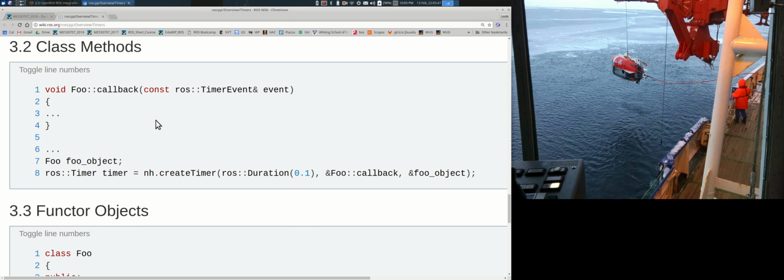For example, in the code that I'll show you in a little bit, we know that the joystick generates joy messages only when you move the stick. It doesn't generate them continuously. And so in my sample node, which is the same thing that you're going to be doing, I chose to subscribe to the joy topic, but then I generated commands to the robot at, I don't remember what it was, like 100 milliseconds regularly. So it would generate a continuous stream of commands because the robot has a dead man timeout: if you don't send it commands for, I think it's 2 seconds, then it'll stop.